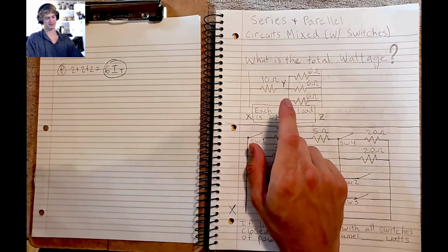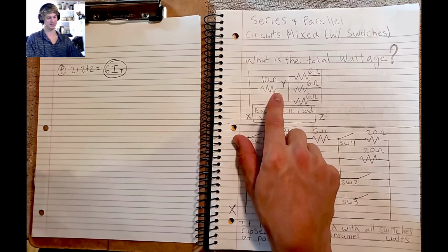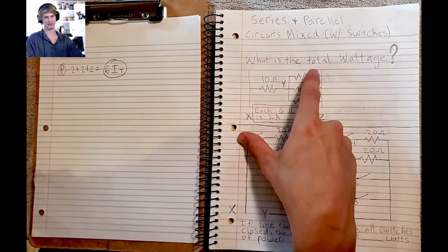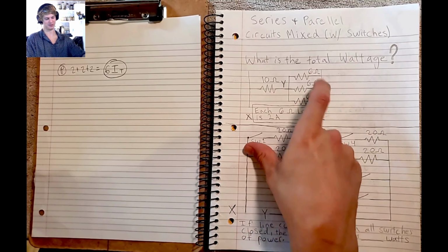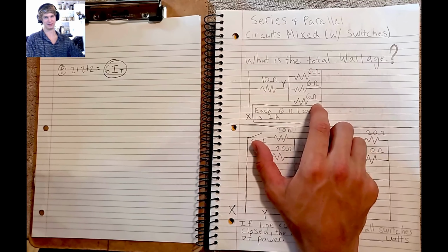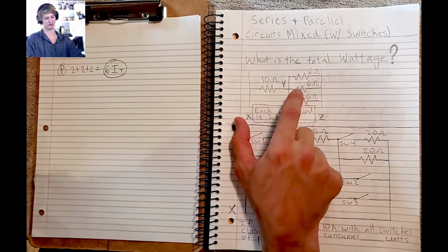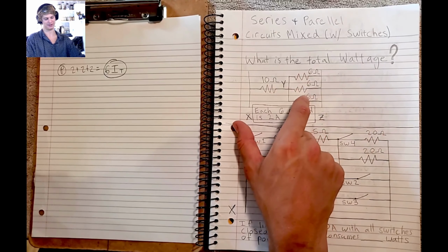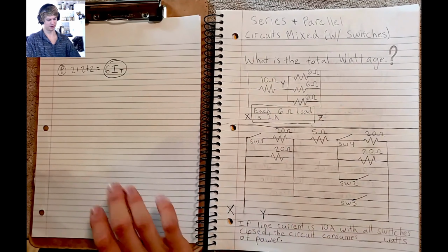So that also means if I knew originally that this had 10 amps going through it, and I didn't know what these had, since these are wired in parallel to this, and these all three have the same resistance, I could have very well just gotten this number and divided it by 3, since these are all going to add together to equal this. Okay, so that's just good things to comprehend.